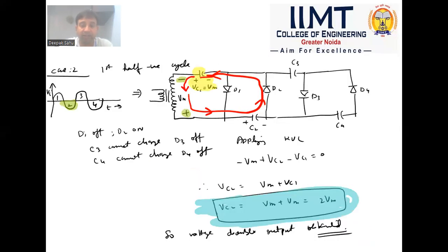Now moving on to the next. Since the capacitor charging and discharging time is kept high, here we can see the first negative half cycle being taken. Now the polarity is changed in reference to area 1. Capacitor C1 is already charged with the given polarity. So with capacitor C1, D1 is on and D2 is on. As soon as D2 gets on with the external circuit Vm as per the given polarity, current flows through the dotted line and C2 gets charged with the given polarity.